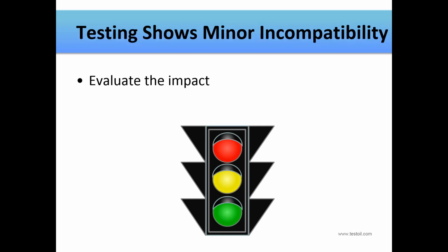If the results show minor incompatibility, you might just need to evaluate the potential impact, such as does the mixture show decreased ability to resist oxidation? And will this result in shortened lubricant life and therefore increase the cost over time due to more frequent oil changes? Or is it a certain performance characteristic that we can get past and deal with? And if it's not something you can get past, then you might want to look into doing a different replacement lubricant.